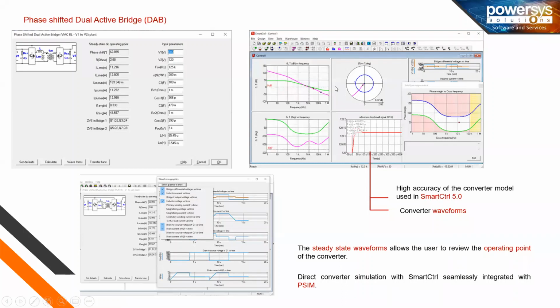The dual active bridge has voltage control mode and current control mode using the ER load. If you want to add a battery load, that is a voltage source with a series resistor, and it is included in this latest version. We also added the DC bus connection, which can be used with the voltage control mode with ER load. In addition, there is an alternative DAB control, where you can add the voltage control mode and the resistive load, which is also included.